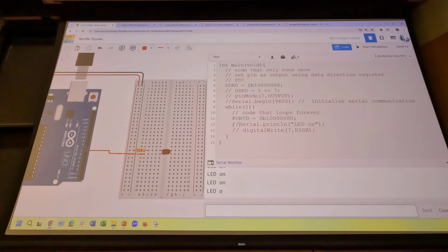Okay, you can use it to print out variables. So we'll get to that more as we progress here. But for now, we just want to make this thing blink, right? So we're going to do _delay_ms(1000). That command just causes a delay in milliseconds.